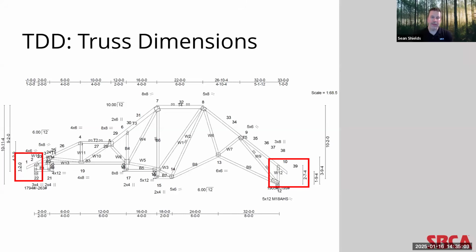This is an area where, in talking to component manufacturers, building designers can really help with accurate truss design. They can do this by calling out the desired wall heights and roof diaphragm heights. By doing so, truss designers can ensure that heel heights remain consistent even as different roof planes come together in a system. As you look at trusses like those on the screen, you can imagine that as the truss profiles change from truss design to truss design,